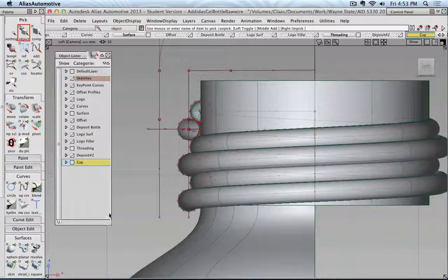There's only one thing missing here, so maybe I can do this with the CV curve again, left and control click. I move with the right mouse button a point down, middle mouse button, move it to the left, control click and snap it to this point so they're vertically lined up, and then control click, snap to it. So I have a very primitive tangency sketched in here.